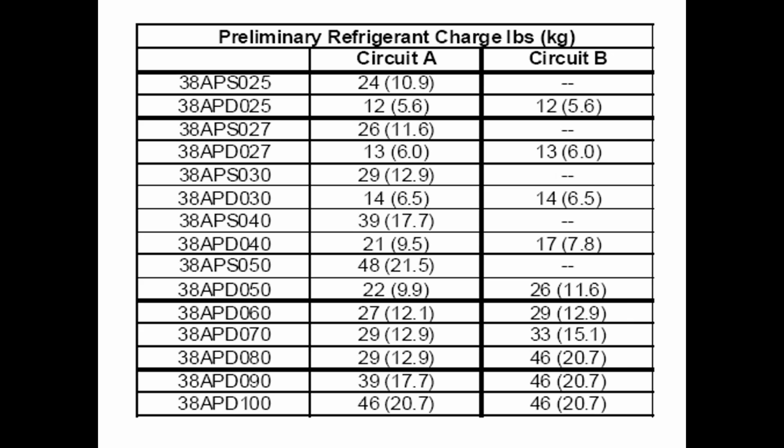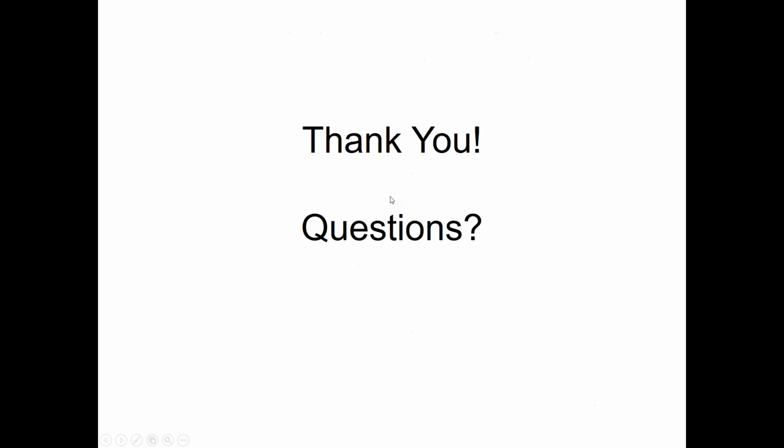Plus, you also have to look at the weight of refrigerant in the evaporator coil. Because again, in the commercial coils, we're talking about more refrigerant than in the res coils. And even in little res coils, you'll see a chart in the evaporator coil manual that will actually increase your charge. There's actually a weigh-in charge for the evaporator, but it's very little. It's like maybe a couple ounces here, a couple ounces there. It's not much. But commercial machines are much larger, and it makes a bigger difference in refrigerant charge.